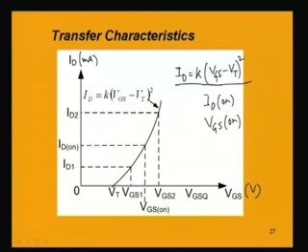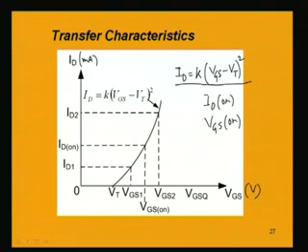Now, if we know these two values, immediately what you can find out is the constant K, the fabrication constant K, because if we look into this expression, K is equal to ID by (VGS minus VT) whole square. VT is known, it is given in the specification.